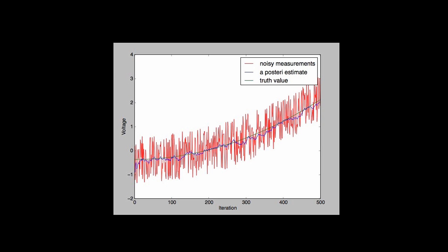Alright, we've now seen sound processing, or how sound looks. If we look at sensor inputs, they work in the same way. Here, the green is what they wanted to measure, and I just screenshotted this from the internet. The red is what they're actually measuring. The blue is an averaging filter. I suspect they tried to get the noisy measurement as close as possible to what they're actually supposed to measure. So if you want to design a filter for this, you first have to analyze it.